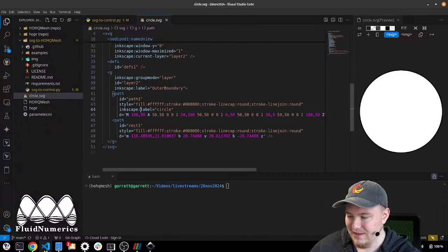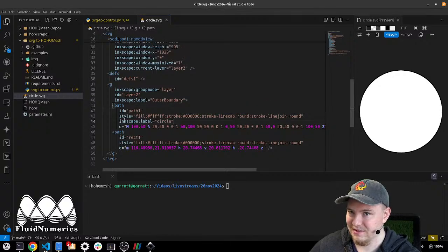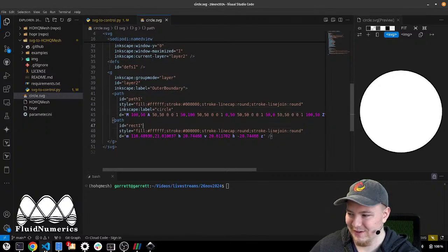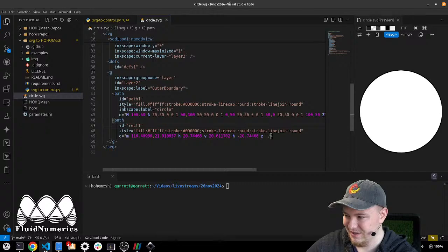It is quite convenient for the way the SVG path tools parse things to use Inkscape label, but it is a little more difficult to rectify things if you're just relying on ID. This is part of why it's Inkscape-only compatible, where you should do all of your SVG drawing in Inkscape, because we rely on this Inkscape label attribute.